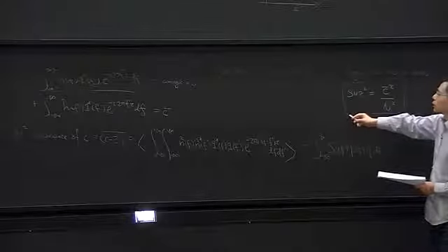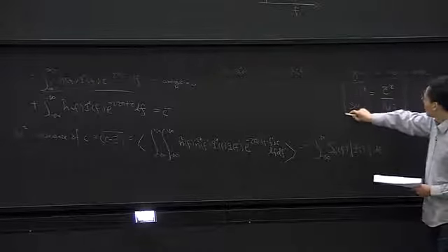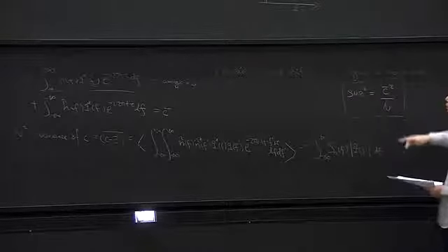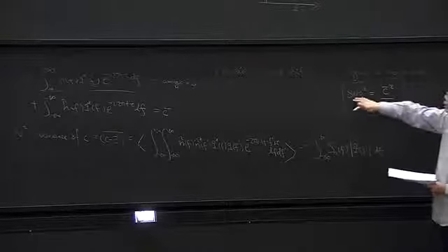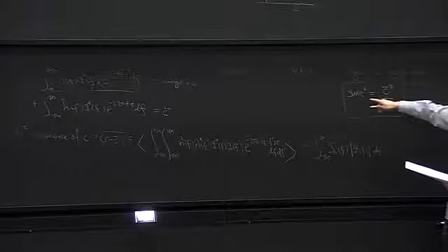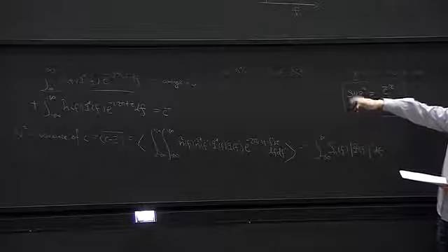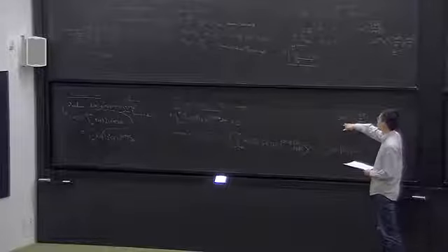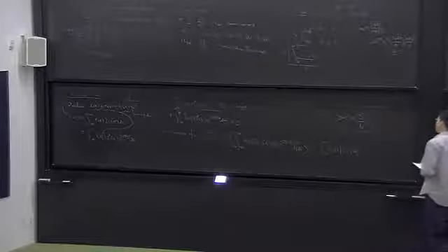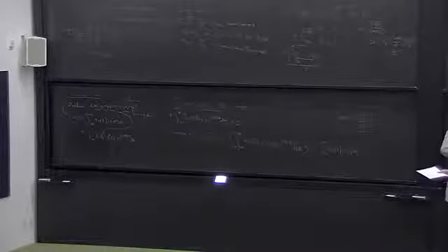In principle, we want to maximize this, right? For a given noise level, we always want to maximize the signal part. So we want to maximize this so-called signal to noise ratio. Of course, this signal to noise ratio depends on the filter function Q, because all other things are already fixed, but we can freely choose the filter function Q here. So the question is, how do we choose the optimized filter function Q?